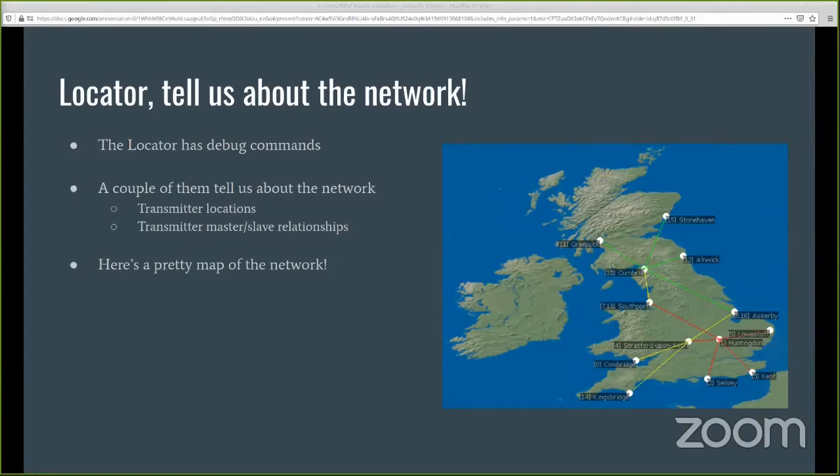a location map of all the transmitters, and you can see that on the right there. Huntingdon is actually the slot 1 master. So there are 2 chains. Huntingdon transmits slot 1, but also transmits the timing information for the whole of chain 1. Around about the Midlands, it would switch to chain 2. The receiver realizes it's crossing that line and switches to using Cumbria as the chain master, which is on the 144 kilohertz chain. And again, Greenock, Alnwick, Stonehaven, and Asserby are all receiving the signal from Cumbria and mirroring that to allow the receivers to navigate.